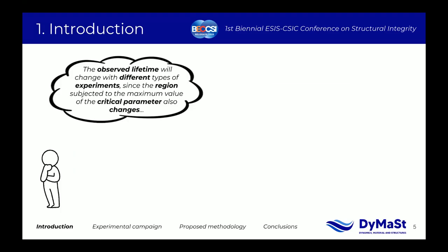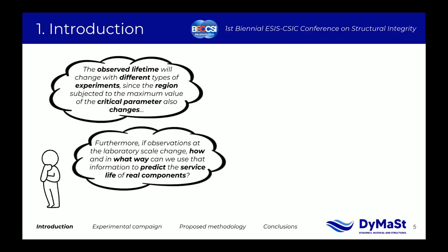For example, regarding the fatigue life predictions, if we test the same material using different kinds of tests, although using the same maximum stress value, the fatigue life that we are going to observe experimentally is going to differ, since maybe the region subjected to the maximum stress value is different.